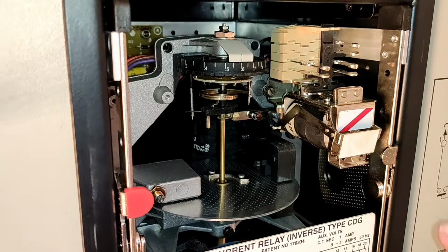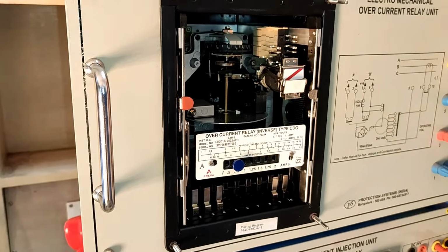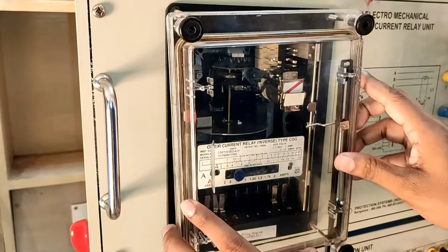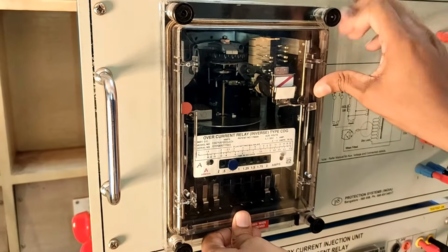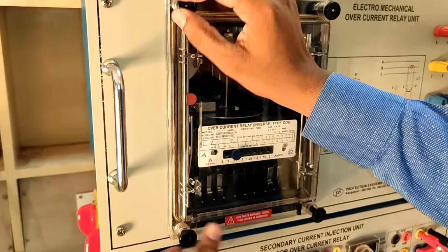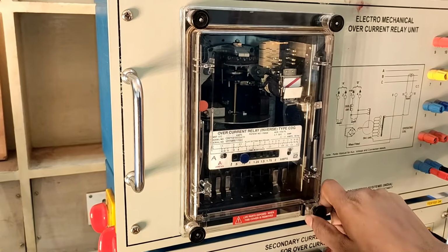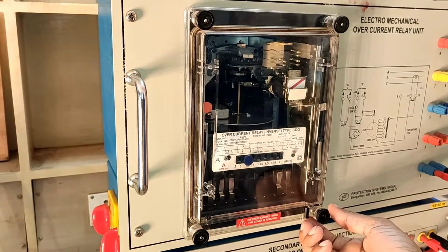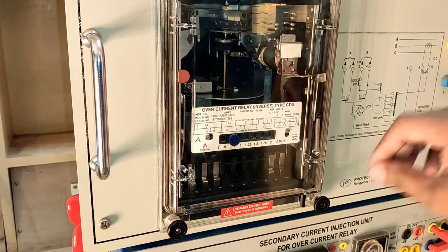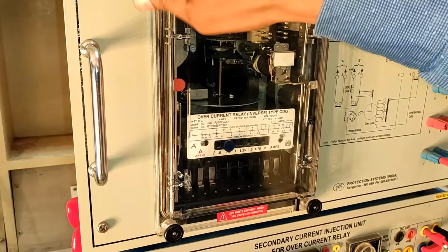As I told you earlier, this is a flap. This is the trip signal indicator of the relay. Right now it is showing the relay is tripped, but even without this indicator showing a trip, the relay can operate. It is only an indication for any user that the relay has tripped or not. So how to reset? There is this part, and we have to push it like this. Now the relay is reset. This is only an alarm type of signal. Without this also, the relay can work.